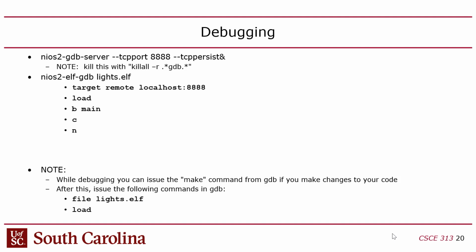That's not the, remember with UART, there's the baud rate and then there's the data throughput, right? JTAG might have a 5 megahertz or 5 megabit per second baud rate, but you have to deal with the overheads of going through the JTAG protocol and the UART protocol and the USB protocol. Right? And you're also routing this through soft logic that's running at 50 megahertz on the chip.